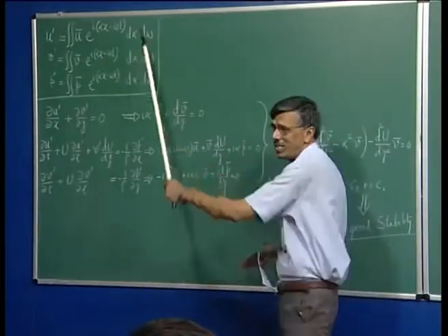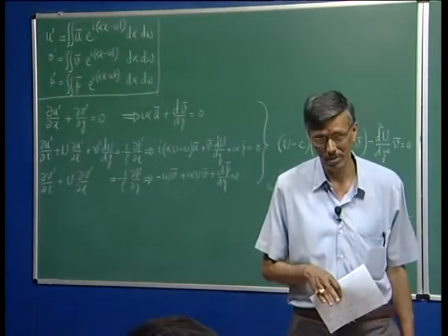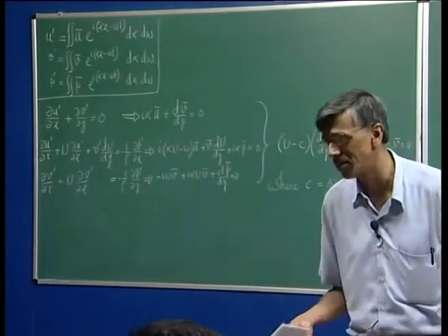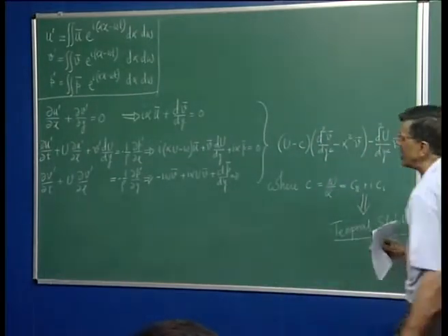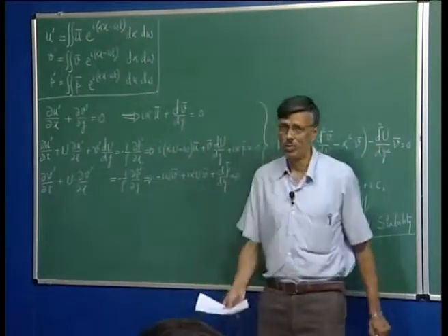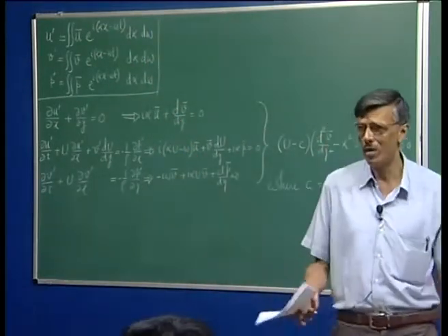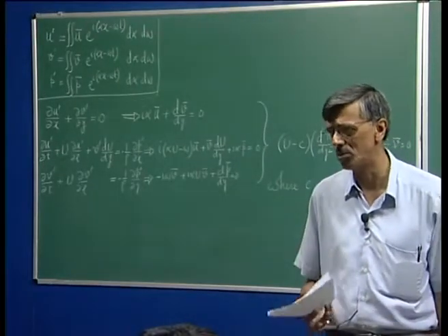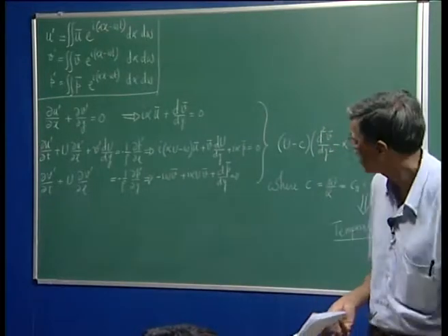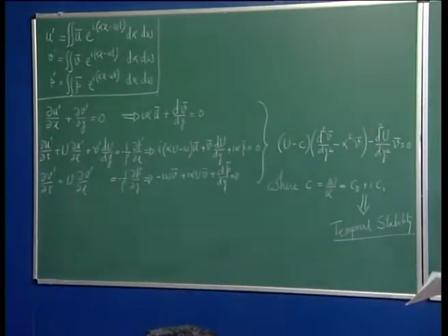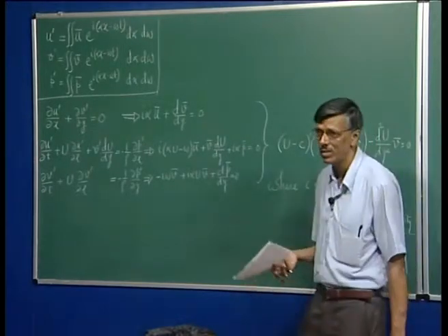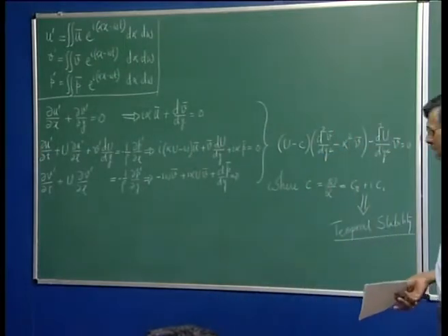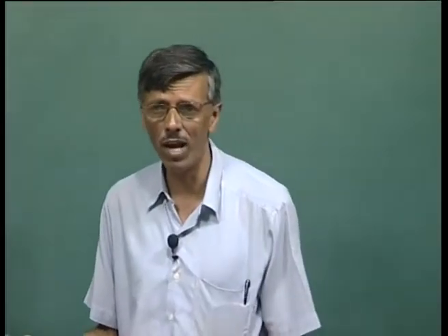What about the time variation? Omega also can be a complex quantity. The real part will, of course, once again define the phase. The imaginary part, now because of this additional minus sign here, if it is positive, is going to be unstable for a downstream propagating disturbance. Whereas, if it is negative, then for a downstream propagating disturbance that would correspond to stability.